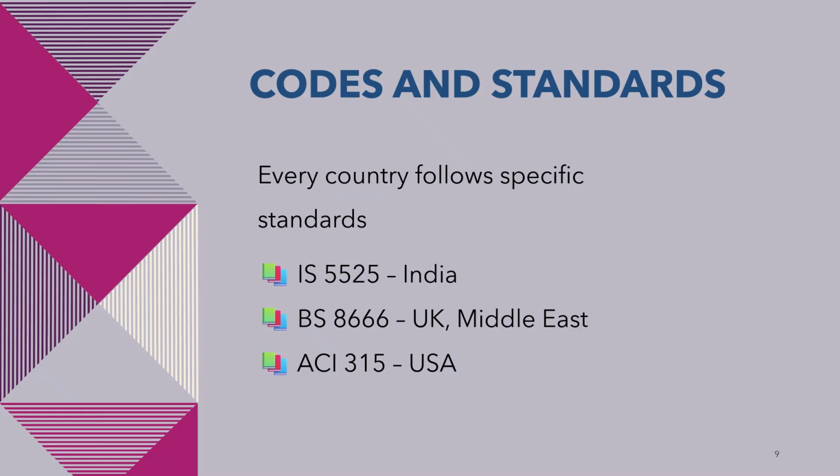BS 8666, United Kingdom and Middle East. For projects in the UK and many Middle Eastern countries, the most widely used standard is BS 8666. This standard specifies shape codes, bar scheduling rules, dimensioning methods, bending requirements, and standard notation. Since this course focuses on British standard rebar detailing, we'll be using BS 8666 throughout the upcoming lessons.